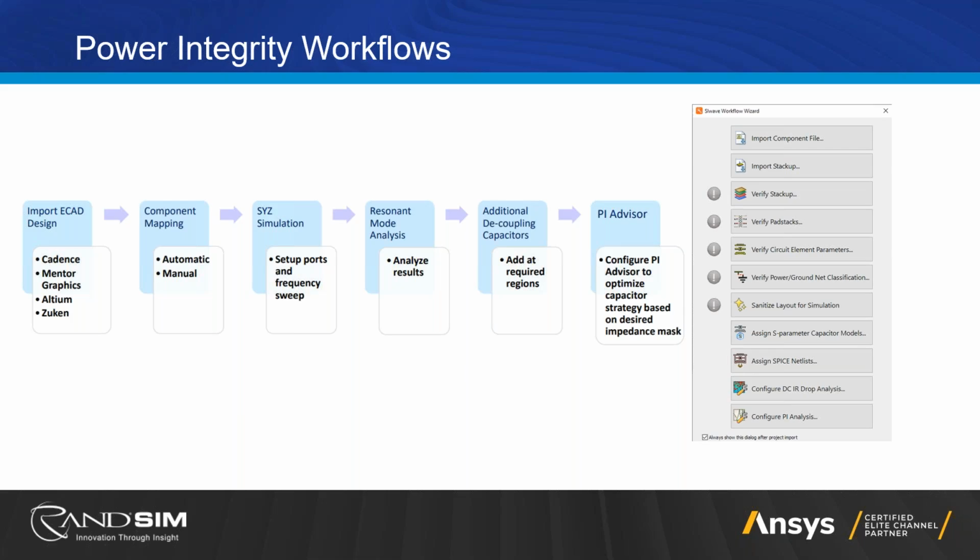And the nice thing about this is it's built from start to finish for power integrity simulation. So you know exactly the steps you need to walk through in order to go from importing in your board to getting those decoupling capacitor values and components to be successful. And what we have on the left here is really that walkthrough and what we're going to be discussing in detail today. I am going to take an aside to talk about DCIR and thermal.